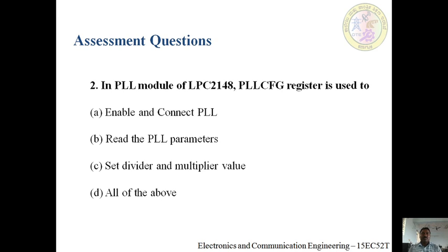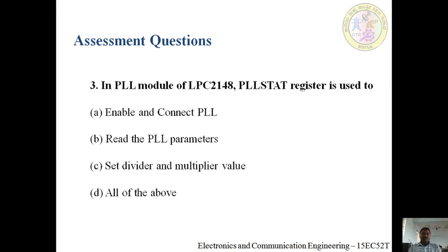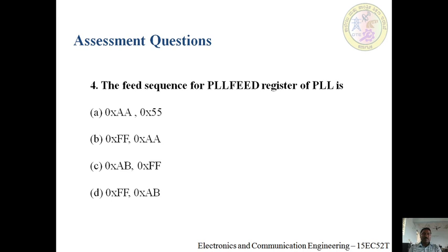As the word configuration comes, you need to remember the multiplier and divider values, to set the divider and multiplier value. Then in this PLL module, the PLL stat register gives the PLL parameters. What are those PLL parameters? Multiplier and divider values, PLLC and PLLE enable and connect bits, and the PLOCK bit.